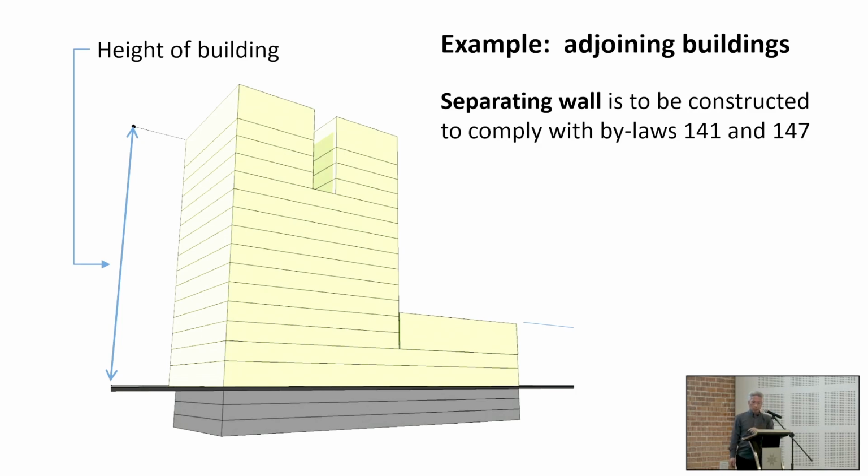Now, where a separating wall will come in is, if you build a separating wall, you still have all your services able to cross. You still have your pipes, your flues, your ducting that can cross, provided, of course, you have the fire dampers and the fire stops and all that. You can still cross, accommodation crossing, you can still do that, but provided your shutter is fully fire rated and fully insulated and it comes down when it's required.